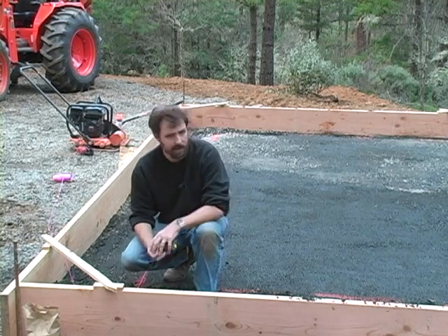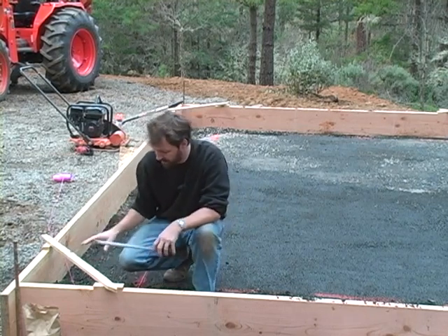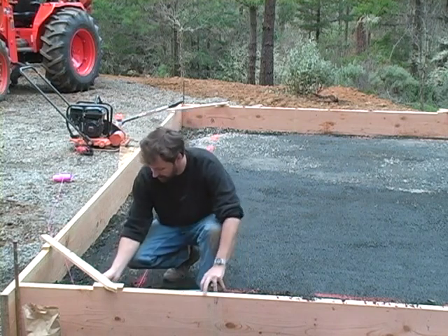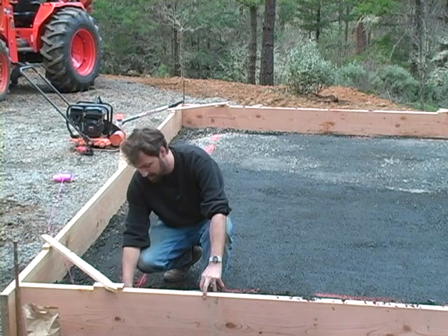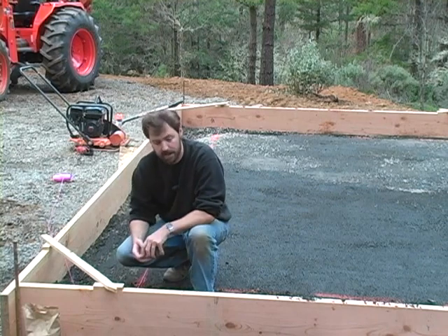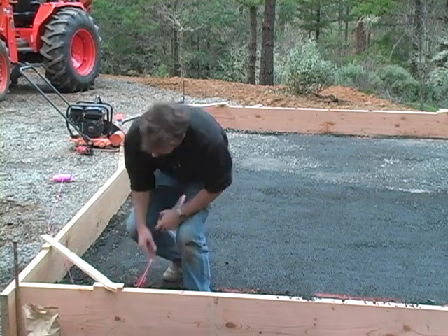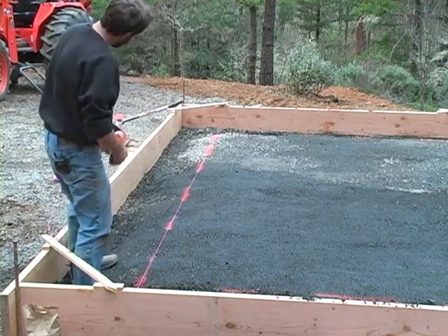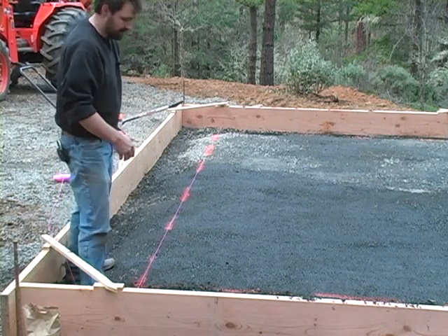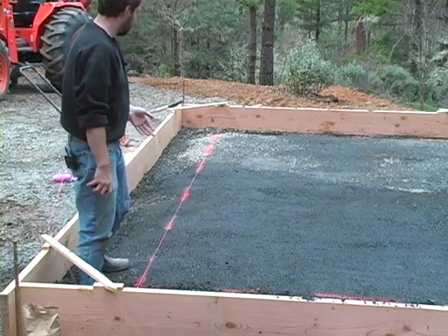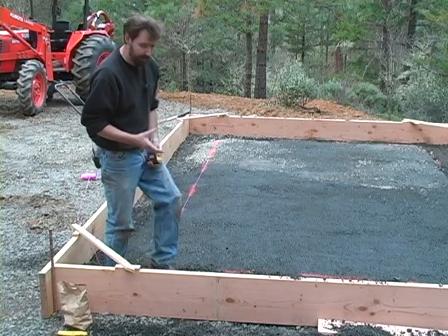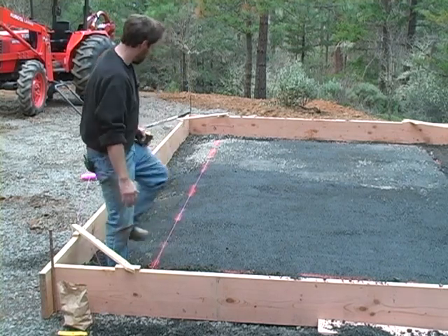Now that all the compaction is done, I want to start cutting out my footings. This is a larger footing than normal. This is a 19.5 inch wide footing because it's for a load-bearing straw bale structure. So I come into the corner and measure out 19.5 inches, and I've placed a screw at an angle at the bottom here. And I've done the same at the other end, and for every corner I measure out that distance, 19.5 inches. I can then run string lines from one screw to the other, straightening out this end, and then I spray paint on here with some bright paint the area that I need to cut out. Then I can just go back through at this point with a gravel shovel and just cut level back from the footing all the way across. So we want to have a uniform thickness and a uniform width across this footing. So this is a great way to define that line.